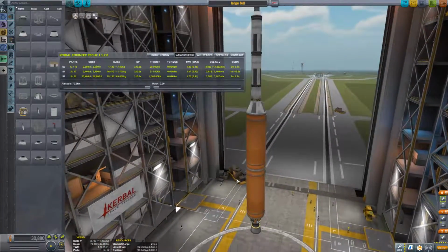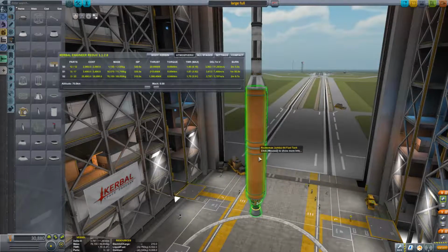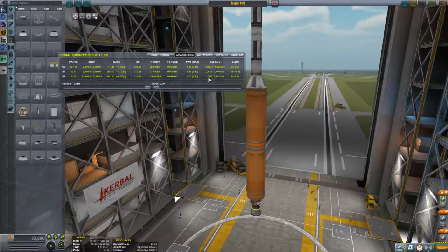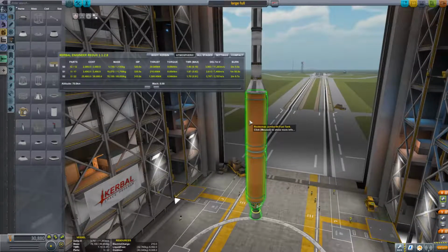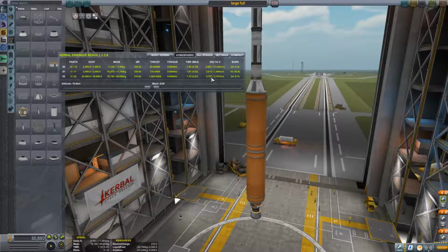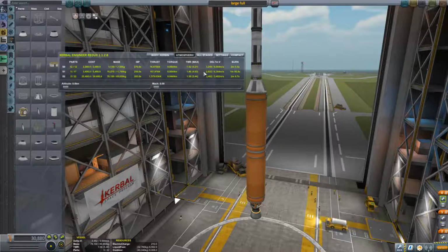Now, the first bit that we're going up, we are fighting gravity, and so we're not actually going to make it a full 3.7 kilometers, and we're also fighting aerodynamic drag, so this is more likely to be something a bit lower, and this tool can help you to simulate, well, what would we lose just from aerodynamic drag, and that's dropped another 300 meters per second or so off of the estimate here.